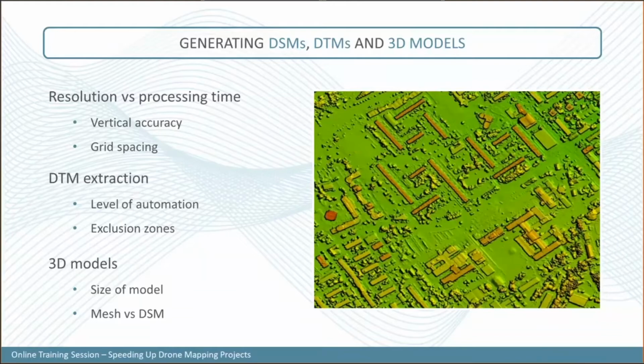This will give you a digital surface model. If you want, you can also derive a point cloud at the same time, but if the point cloud is not mandatory, you can export your surface model as a point cloud at the end of the generation. This really reduces the processing time if you don't need a super dense point cloud but still want a point cloud. You can derive a point cloud directly from your DSM with the export as LiDAR point cloud.